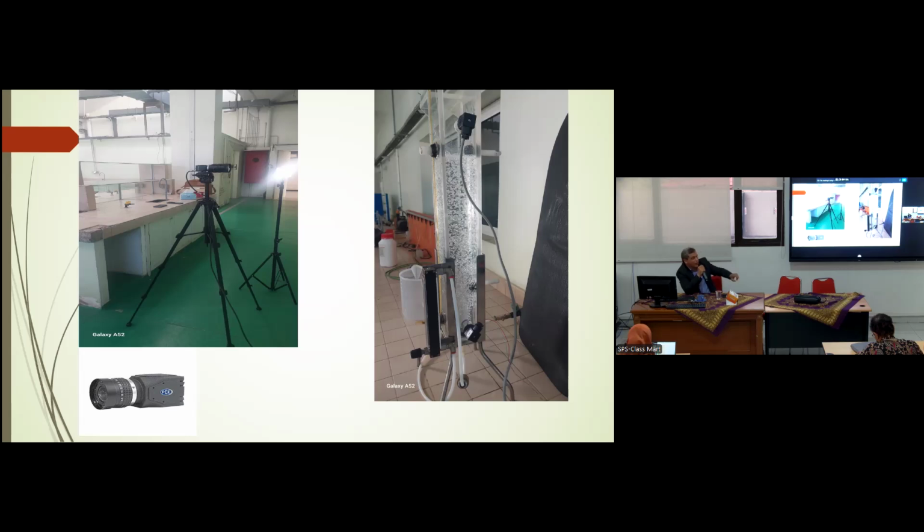For example, I have to remove iron. I can remove iron by ionic flotation, or I can remove iron by electrocoagulation. But in electrocoagulation, we have sludge, and in the sludge there are a lot of pollutants. Here we have the foam. It's easier to use ionic flotation than electrocoagulation.